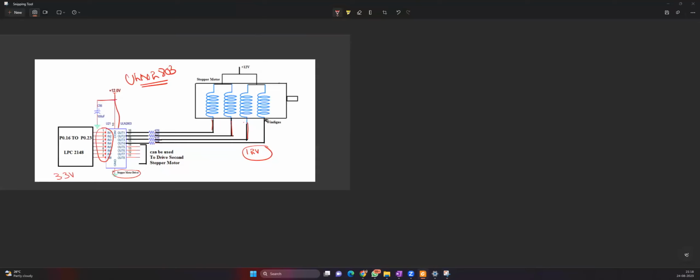So usually in ULN2803, these A, B, C, D are there, right? We have to drive them with various voltages. Like if I want to have clockwise direction, I will drive like 1 0 0 0, 0 1 0 0, and so on. Same way, if I want to drive anti-clockwise, the sequence will reverse. So I will go this way, and this will drive anti-clockwise.